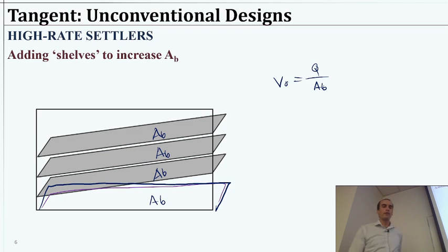So we might call this a high rate settler. In certain special scenarios they're used. It's not super common in drinking water treatment because I think the risks are a little higher if we kick stuff back up, and it's a lot to manage mechanically to collect the particles and remove them without kicking them up and doing all that. So in some scenarios, these are quite useful. It's really smart to use physics that way, but not always.